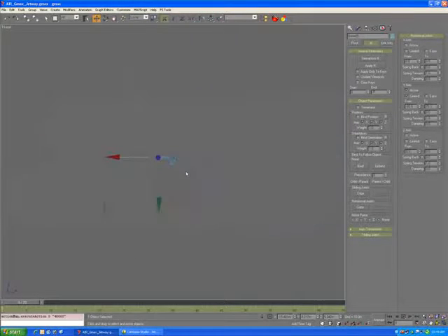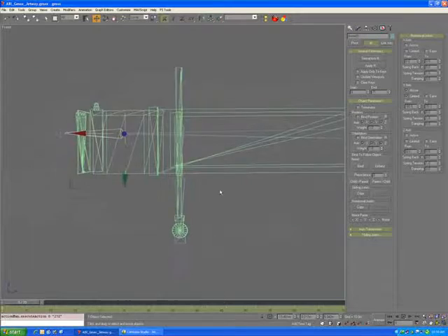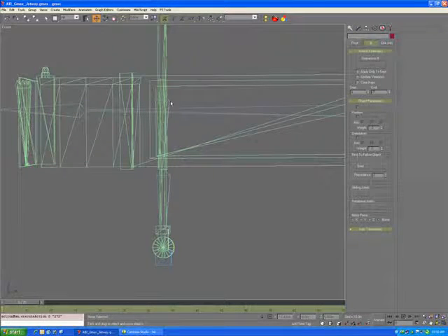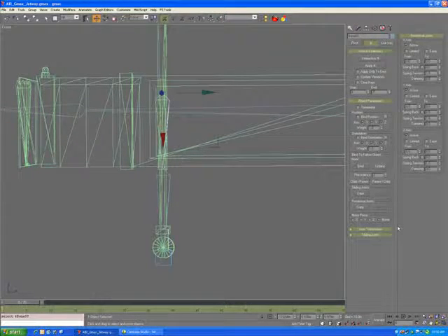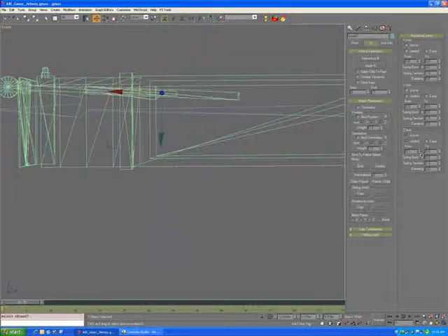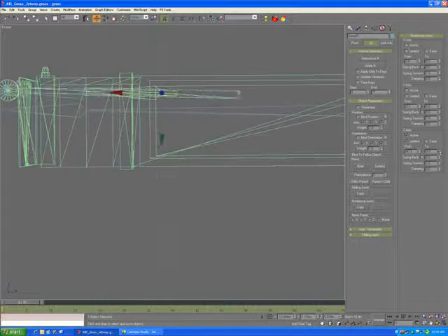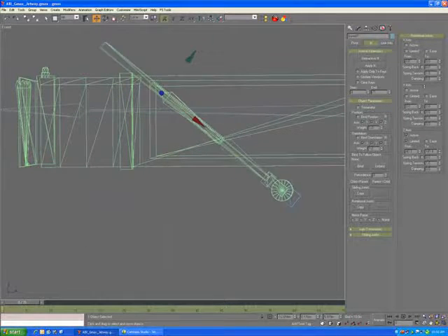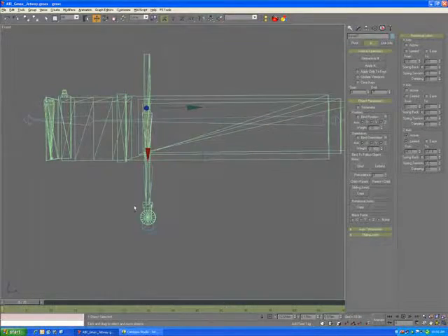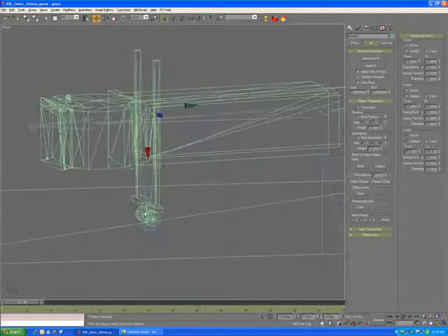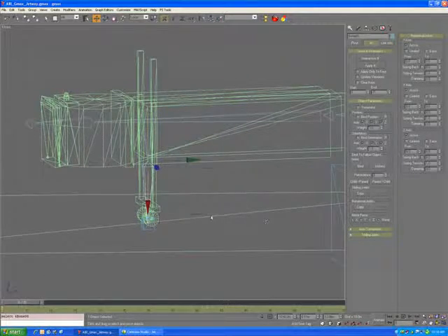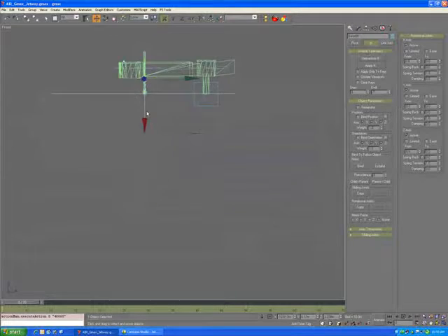So the next step is to do the legs of the jetway, and once again we're going to select this bone here, no sliding joint in this case, and it looks like the z-axis is the one that's rotating, so we'll turn off the y, turn off the x, and limit the z. And so it will go from about there to about right there. And it may never solve to that point, but it's good to just allow it to get that far.